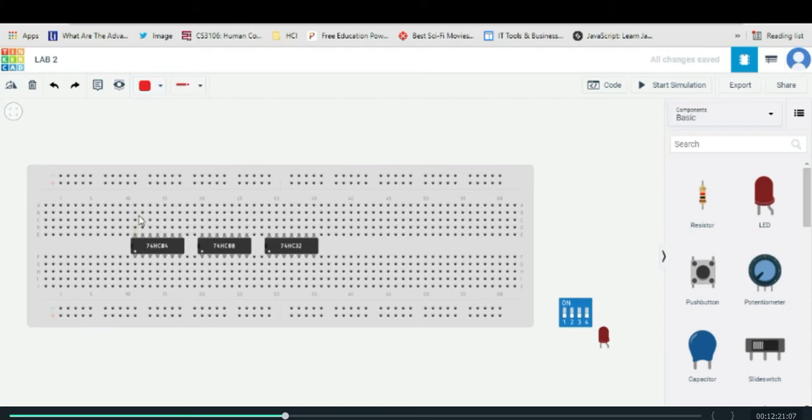So here, just click the hole and then drag it to the power pin of the next IC. Then this one also, since this will be connected to the next IC, just click the lower dot to establish connection and then drag it to the power pin of the other IC. So we already have a common connection with the three ICs.